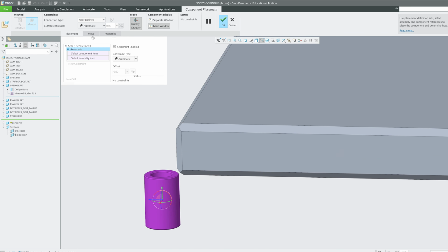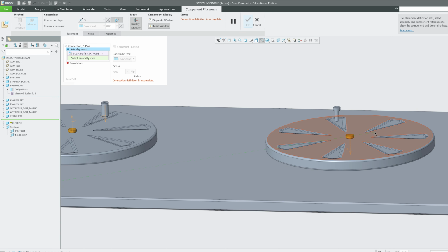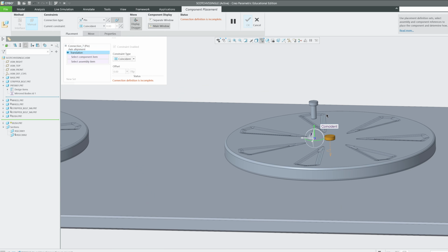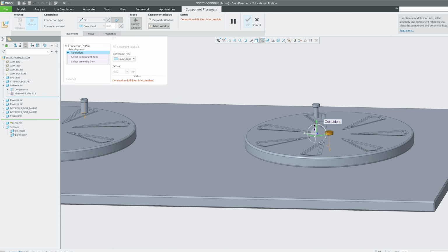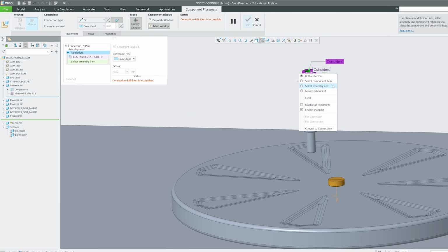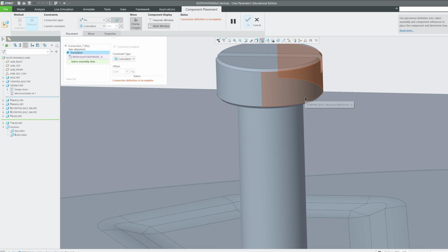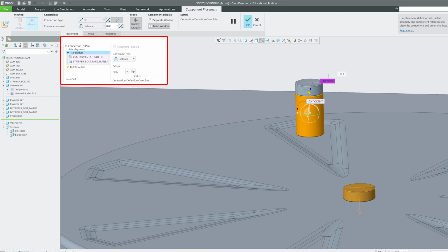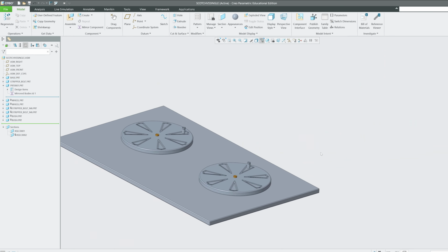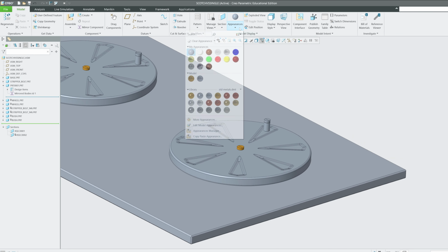Let's do the same here as well. So again, I'm gonna go here and let's make it pin joint. So I am trying to mimic how it will be in actual. So that's why I am making it like this. Oh, I think we already have made axis to axis. Let's make it flat to flat. Let's give it a distance of 0.1.